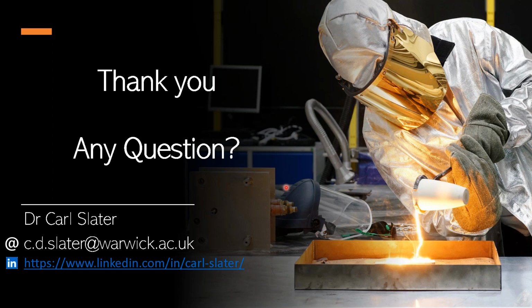So we can either do solidification under no load, or we can do some deformation, some tensile or some compression deformation, but we were really limited to 1,300 degrees there. So again, coming back to the question earlier about quenching, most of what we do is interrupted test, quenching, and then doing cold characterization.